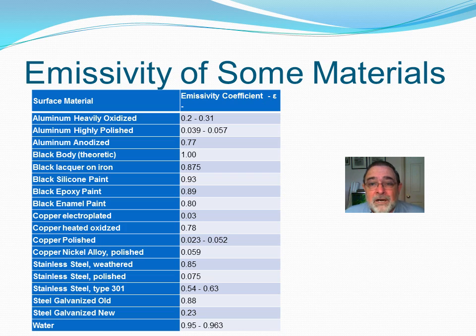Because it's going to oxidize, and when it oxidizes, it's going to lose more of its heat, but it's also going to generate more heat. You become a high resistance joint. Okay, so the emissivity changes over temperature range and with oxidation, but the number rises in the copper from about 5% or 0.05 to 0.78 or 78%.